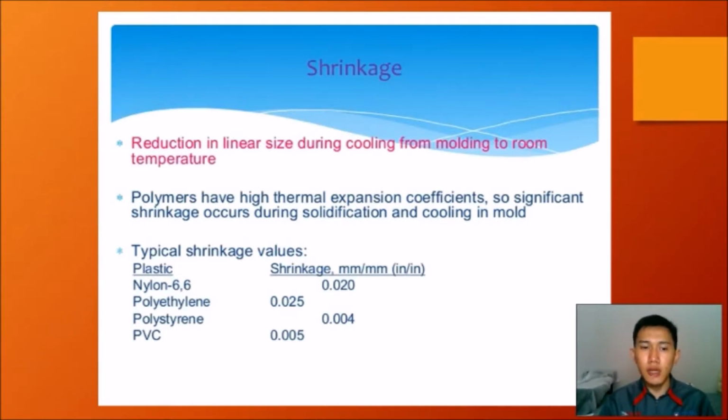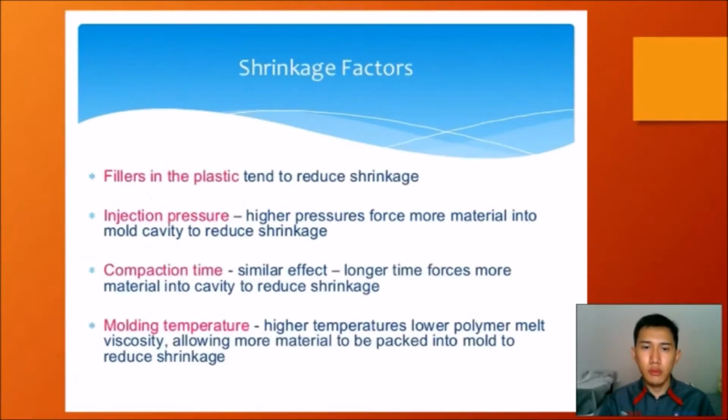Extrusion blow molding. In extrusion blow molding, a hot tube of plastic material is dropped from an extruder and captured in a water-cooled mold. Once the mold is closed, air is injected through the top of the container. When the hot plastic blows up and the mold material freezes, it's able to maintain its shape.